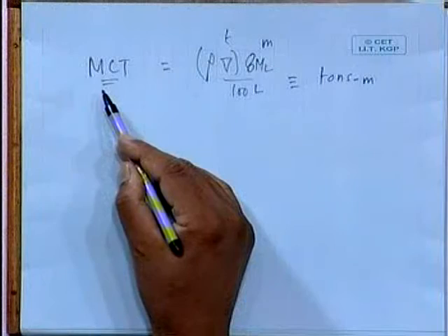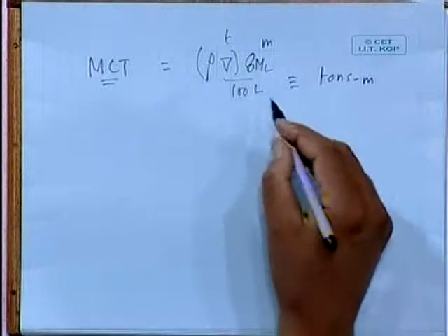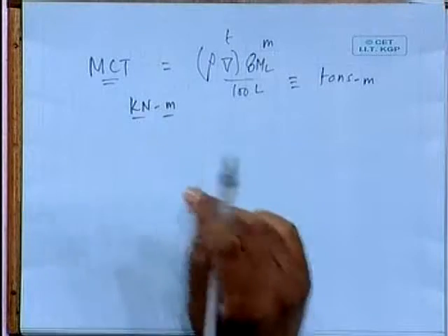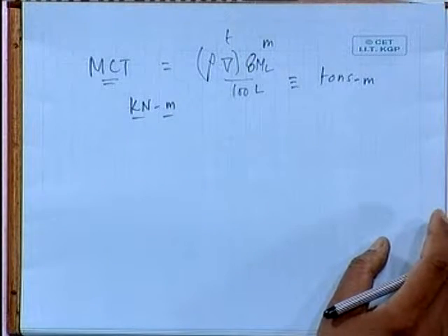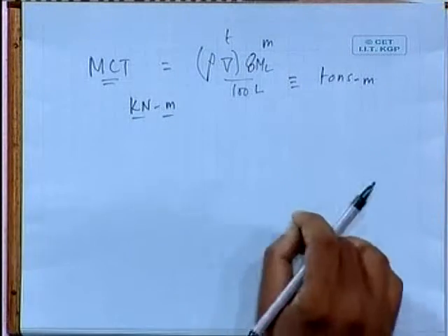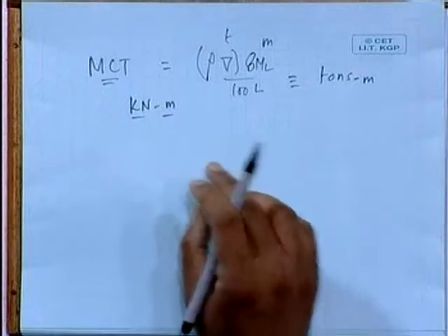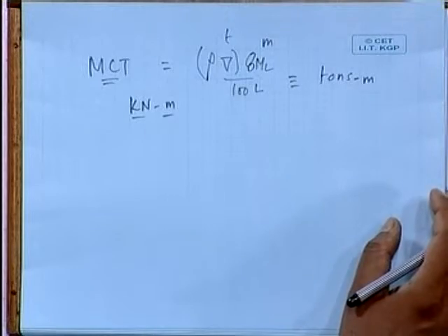But please remember that in many calculations, moment is better represented using kilonewton meter. We have this persistent confusion of force being expressed sometimes as tons, sometimes as kilonewton. In all literature, moment to change trim is expressed as ton meter.